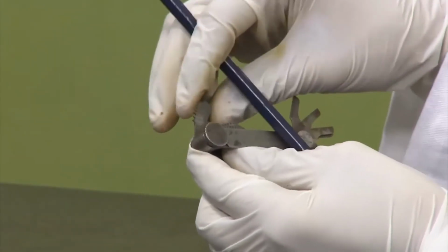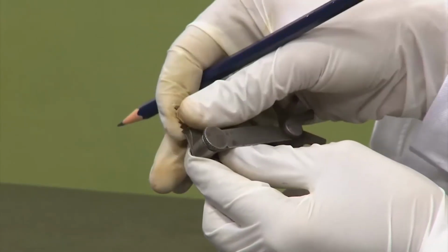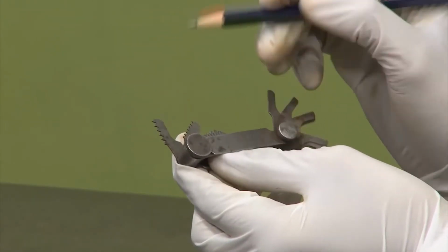So, this feeler gauge or the thread gauge, these small gauges are instruments which are used for very quick measurements, so very quick inferences. This feeler gauge can just tell us what the gap is. We can measure the gap in many other ways, like if the gap is larger, we can use vernier caliper or certain other methods. We can measure the pitch of the thread using other metrological methods, but the thread gauge is one instrument that will just give you quickly what the pitch is.